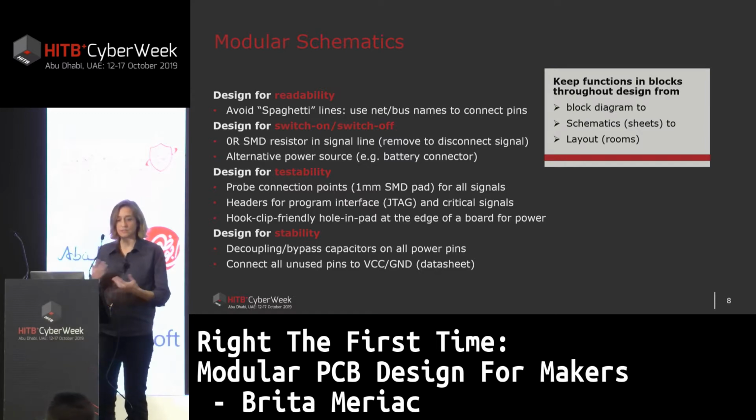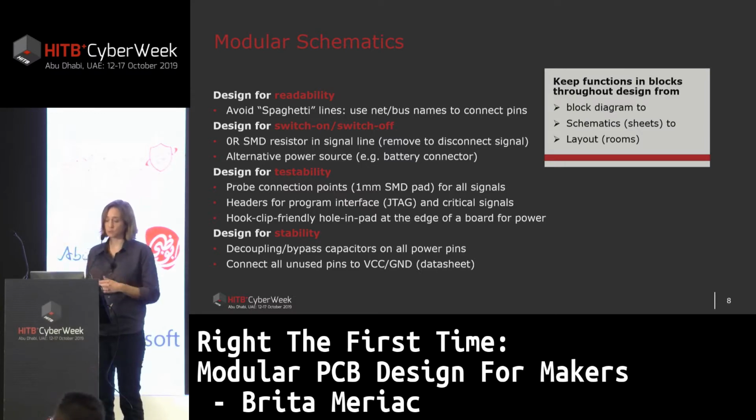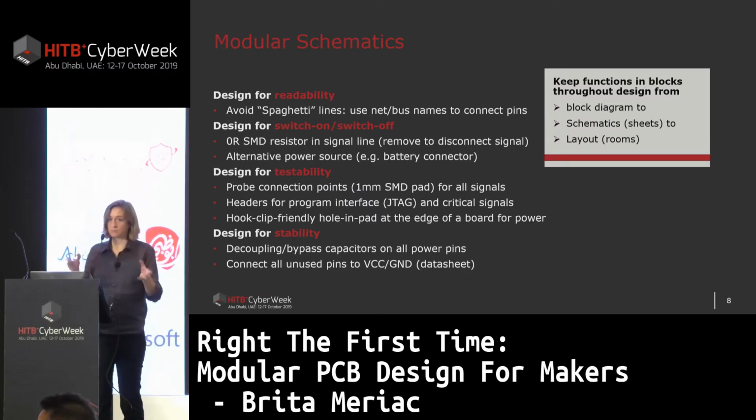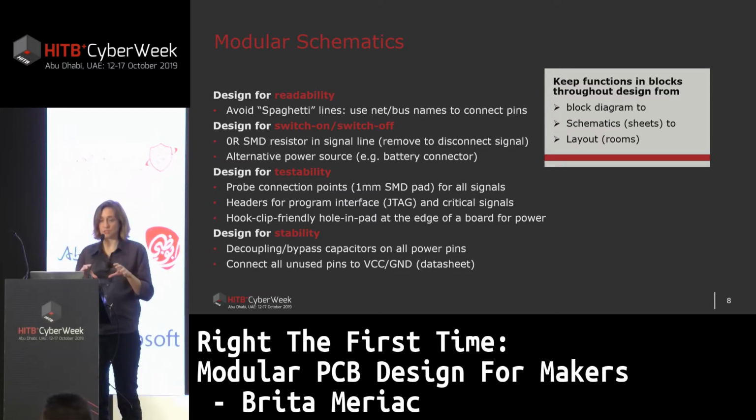So the schematics: create your schematics according to your breadboard. Each function block on a different sheet, and every function sheet connected on the top sheet. And by establishing dedicated names for nets and buses, you do not have to trace every track from pin to pin and create an entanglement of lines which is hard to follow, but you have some kind of readability for your schematics.